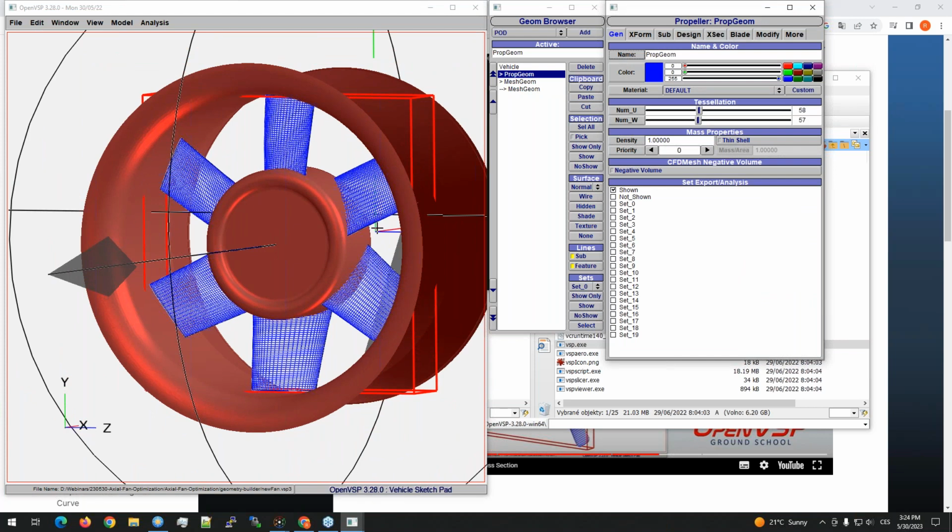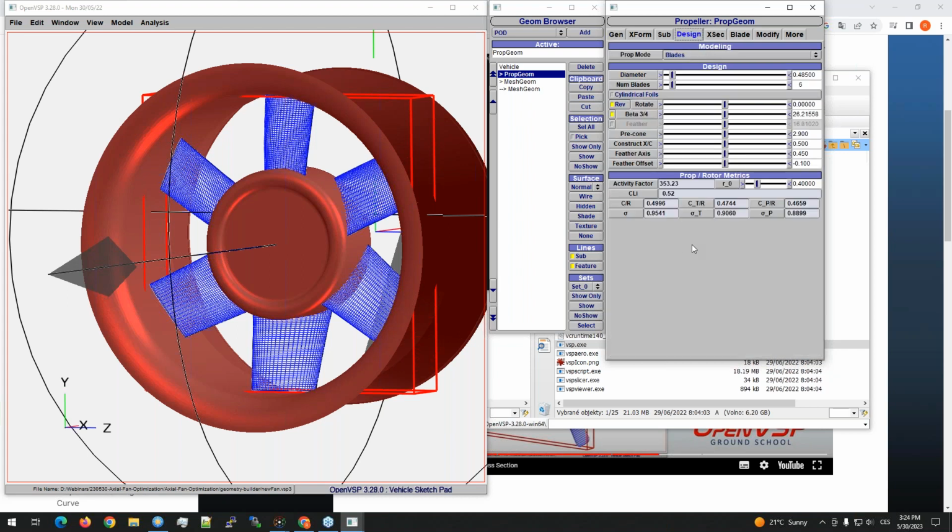Now you can decide what you would like to parameterize. You can change the thickness or the chord length with respect to the radial direction. Here we have chosen 4 parameters which we understand will mostly influence the efficiency. But in general it depends on the goals, on the user's experience, and on the experts who have been developing axial fans for years, so they have some internal know-how about what is best to adjust to achieve better performance.